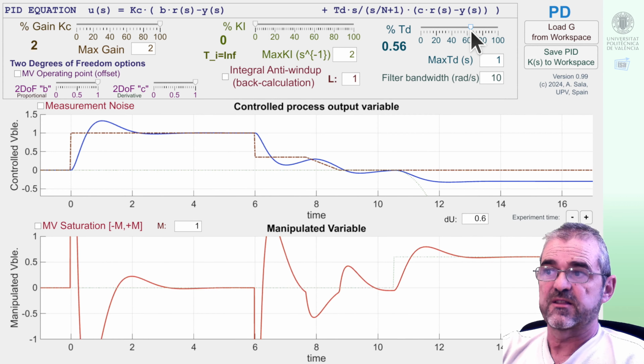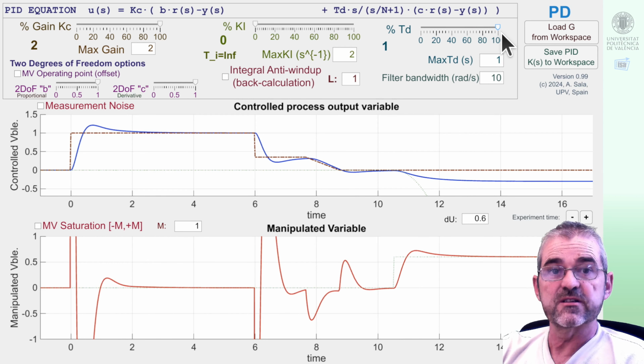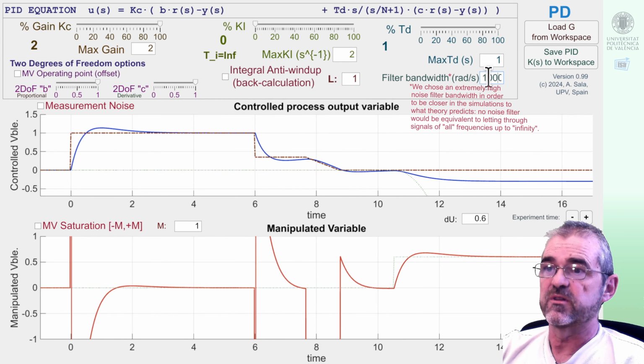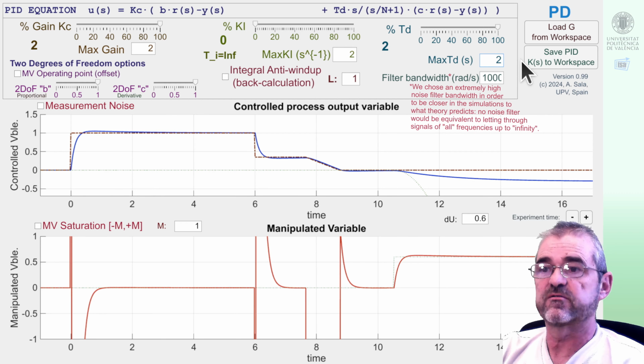Of course, at the start they are extremely damped, so they are barely noticeable, and they are non-existent here. Of course, putting no derivative filter will give the exact response predicted by my theory, so no oscillations, and with stronger derivative action I will have two real poles.